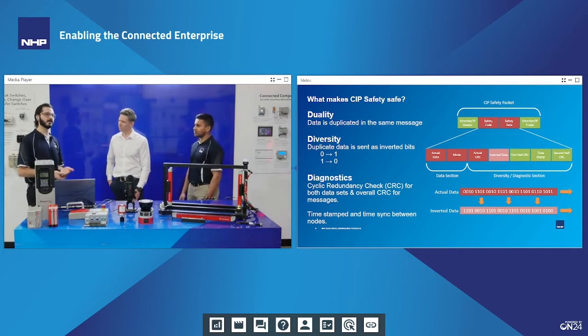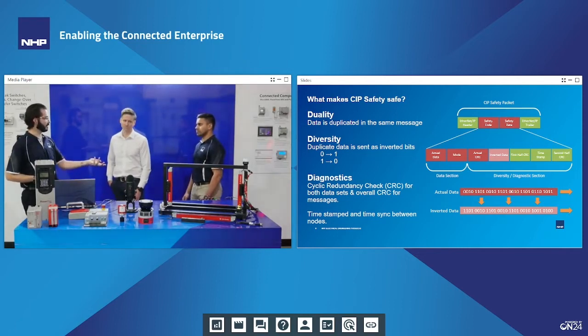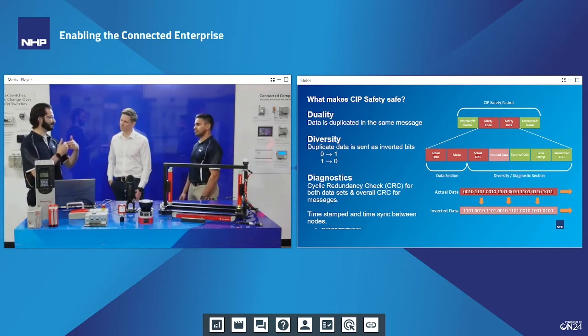I know someone's going to test me, and of course we're live, so Open Device Standard Association, I believe. If I'm wrong, please don't flame me. But yeah, ODVA is the body that developed the CIP protocol. And CIP is not necessarily stuff that operates over Ethernet, but they've also got ControlNet and DeviceNet under the same banner. And it's all the same data structure, it's just operating over different forms of media. So DeviceNet, for example, is over CAN bus, whereas EtherNet/IP is CIP over Ethernet media.